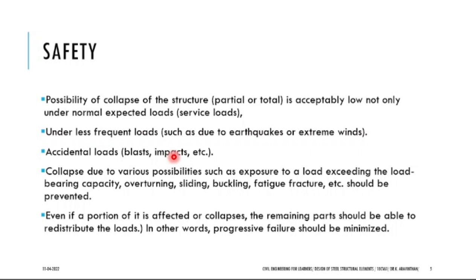When you are constructing a structure in your college premises, that is at Rajarajeshwari Engineering College, you don't need to consider two loads. What are they? Rail load is not occurring here, and another load is blast loading, which is not occurring here. So you should know that when you are nearing a railway track, within certain meters, you have to consider that accidental load, that is blast or impact.